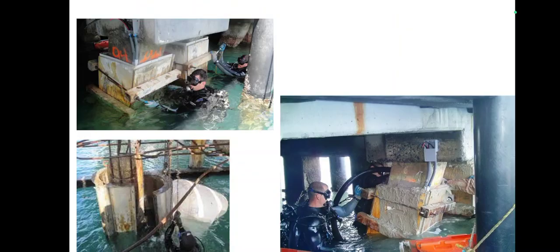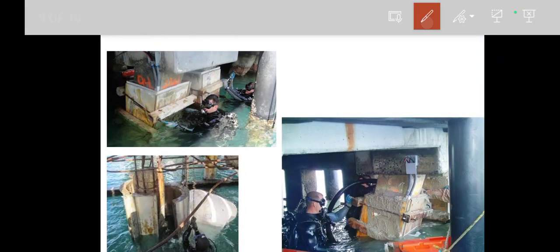Here also you can see some operations showing how the steel sleeve is formed. It is not exactly the steel sleeve. They are using a normal temporary formwork, and once the concreting work is completed, they will remove the formwork. I am not able to get the exact picture of the steel sleeve. Here you can see once the concrete has been poured, it overflows from the surface. By that time they can tell that it has been filled and stop. So this is the easiest technique when compared to other methods.